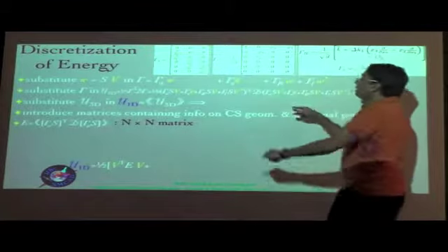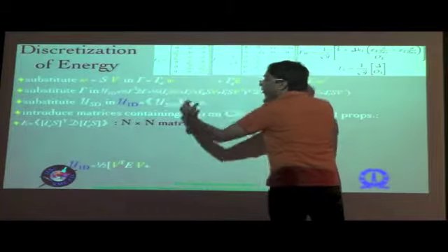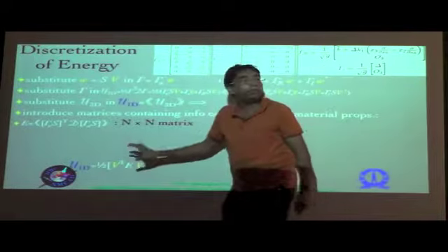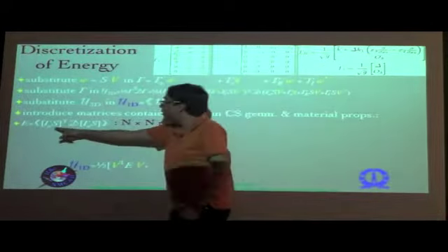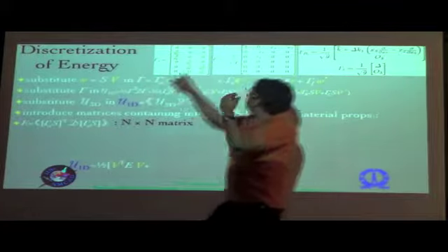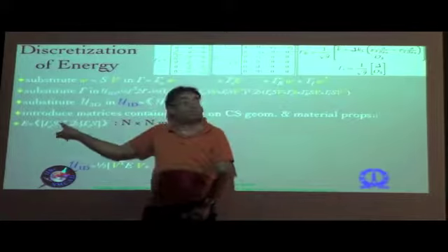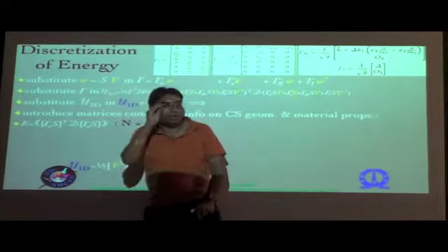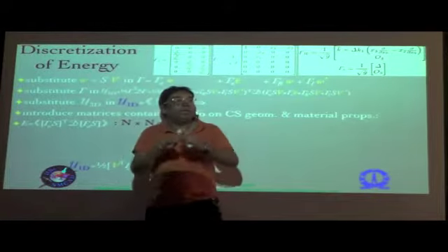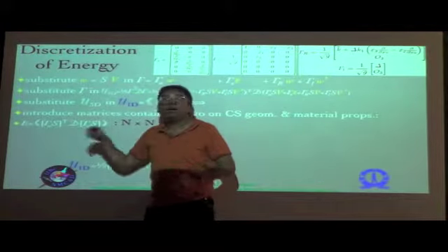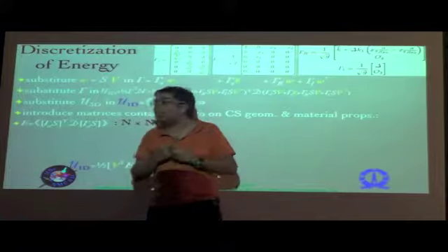Now what we are doing is, basically the rest of the quantities we are clubbing into a single variable, which we shall call as E. Okay? And that E is of course defined in terms of this matrix gamma A, which is a differential operator, acting upon the shape functions. Remember that the shape functions upon the choice of the specific element and the nodal degrees of freedom are explicit functions of x2 and x3.